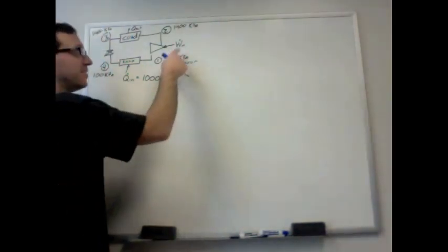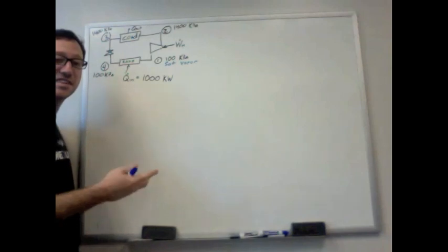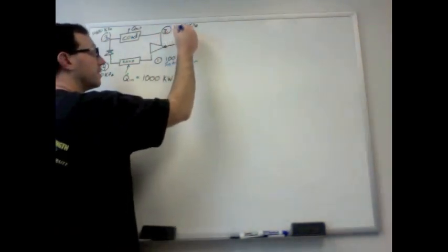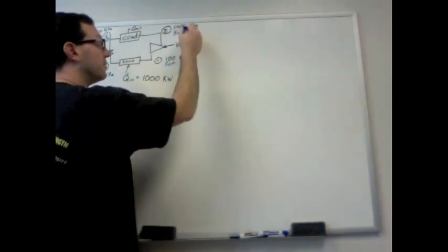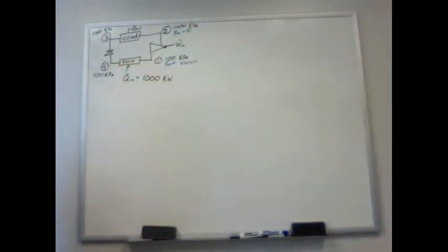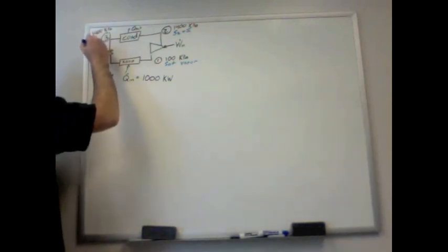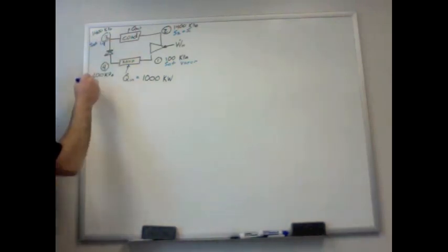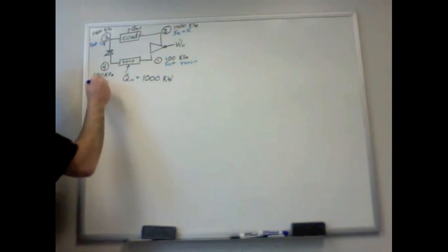The ideal assumption for the compressor is that it's isentropic, a reversible and adiabatic compressor. If it's isentropic, S2 is S1. The phase that we assume coming out of the condenser is saturated liquid. And across the expansion valve, the enthalpy is constant.